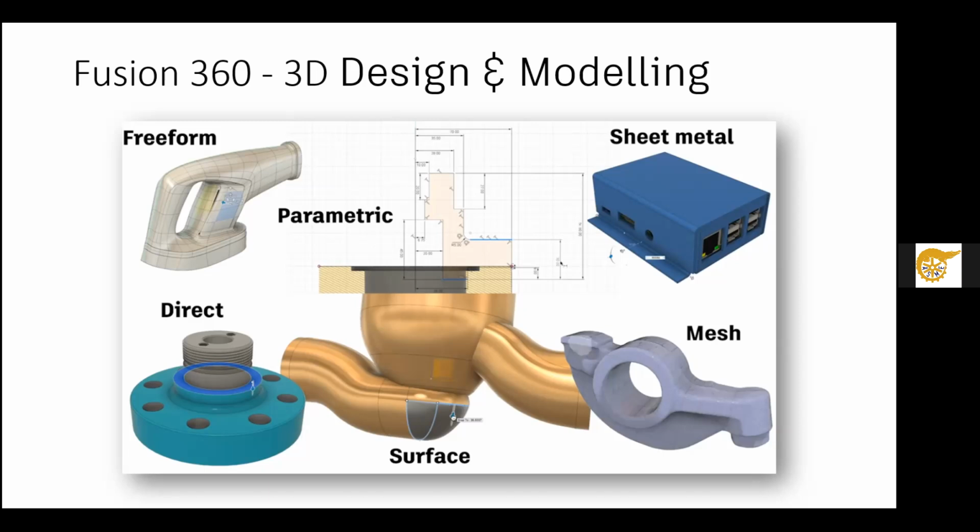And then we have direct modeling, where you can actually take a CAD model that wasn't actually designed in Fusion 360, import it using the AnyCAD tool, and still continue to modify it, right? So you can import CAD data that's not native to Fusion, and you can do things like remove holes or even add holes. You can extend extruded surfaces, delete faces, and other things like that.